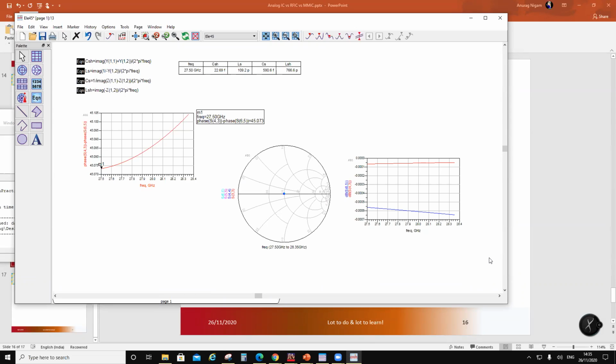So what is going to happen is they design for a certain mismatch. So those formulas have inaccuracy. This one won't have. And as long as VSWR is better than -15 dB return loss, you are okay. If it becomes very bad, like -3 or -4 dB, then your design was wrong.